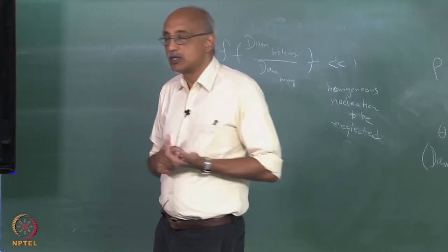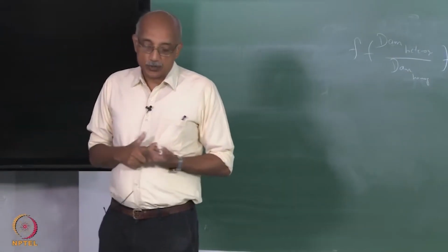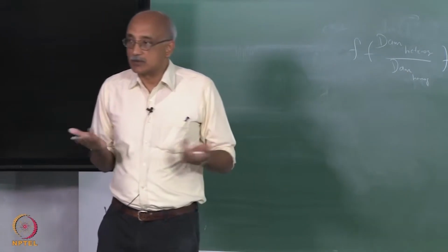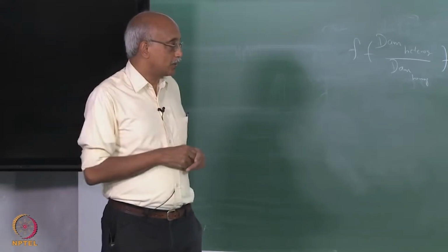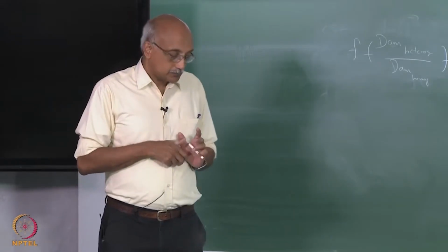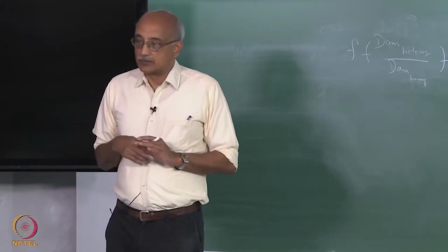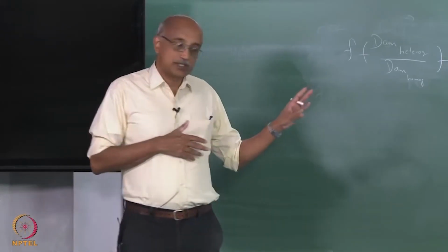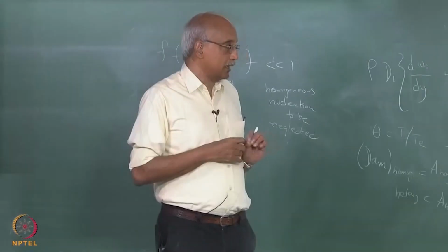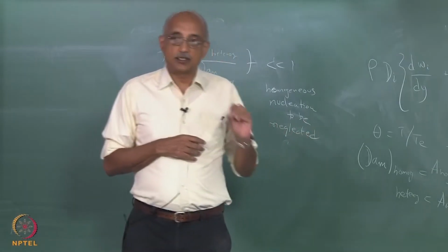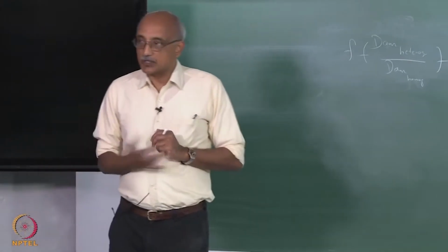It is good from the viewpoint of preventing homogeneous nucleation, but it is also good from the viewpoint of minimizing your energy expenditure, right. The less you heat the substrate, the less energy input you are providing to the system. But it is not something that you can do empirically. The message that I am trying to drive home is that there are ways in which you can systematically analyze a CVD system and actually precisely identify these temperatures that you need to set your substrate at.